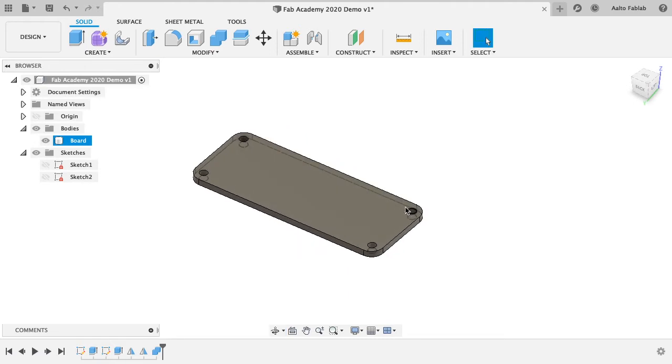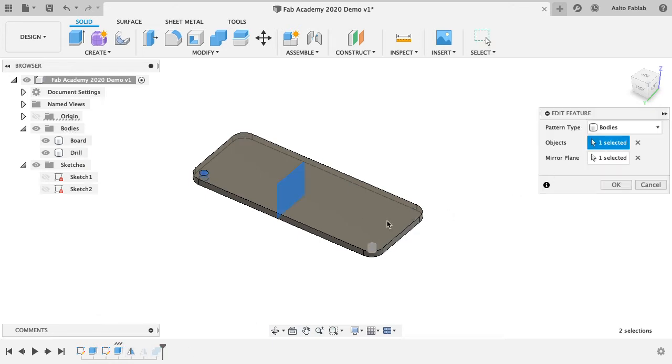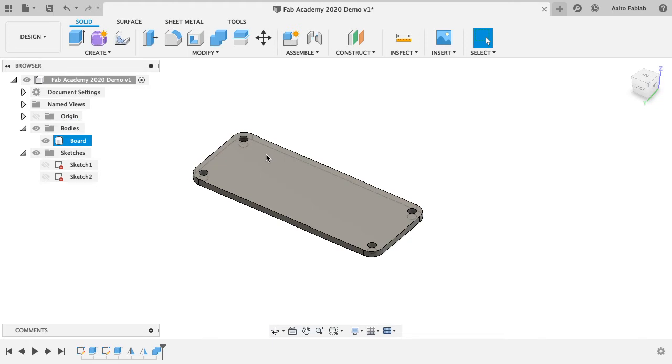What's the benefit of doing it this way instead of doing it in the sketch and then extruding? I think in my case, it's more like the previous experience with it, that sometimes when you add it in the sketches, it can get messy. But if you look on the bottom of Fusion here, this history line makes it very easy for you to control the design later. You can go over to each of these features and you can change things. Basically, I think the issues that I would have like 2 years ago with this would be gone.